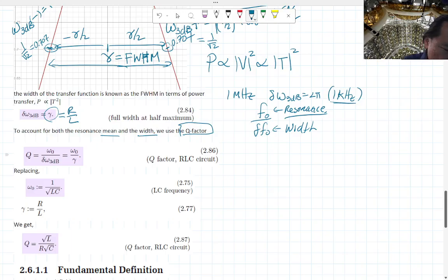factor. So the Q stands for quality sometimes, but it's not exactly that, because the more quality components you have, you may not have a higher quality resonator. It's just picking your components out properly. Okay, so the way we define that is basically the resonant frequency divided by this delta F3 dB that we just calculated, or the full width half maximum.